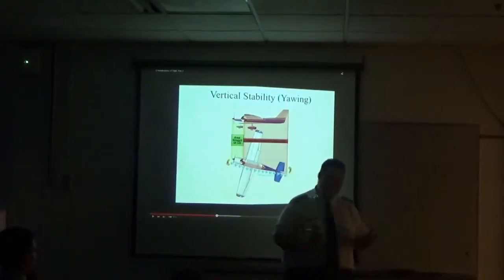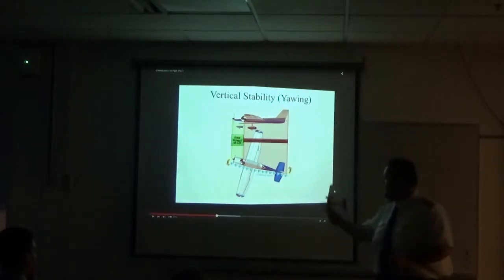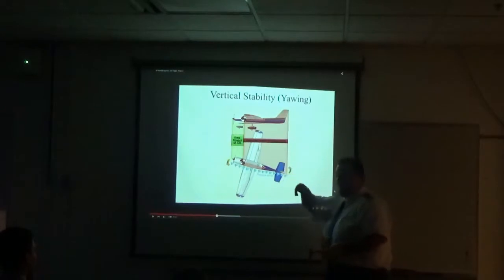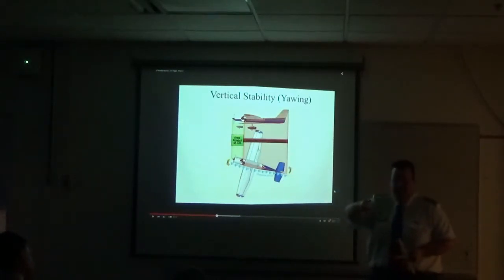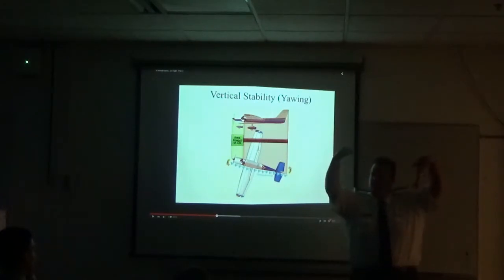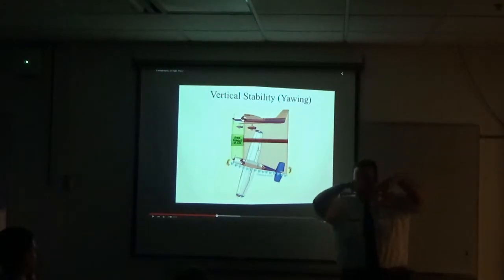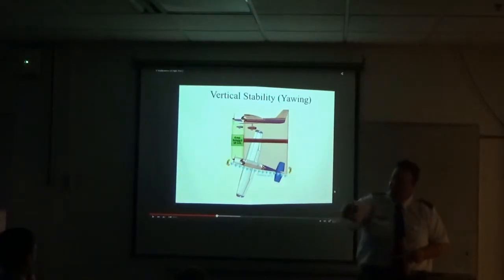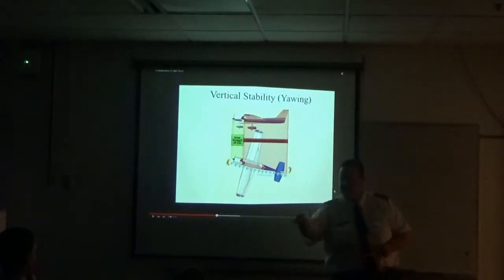Correct. Now, that is usually not a problem with the trainers, especially with the Cessna Skyhawk, because most of the time you have a fuel selector valve, and Skyhawks can have an option of setting it on both, so it pulls equally on both sides of the tank. That's more of an issue with small planes like the Piper, where you have to constantly switch from one tank to the other, usually every 15 minutes of flight.